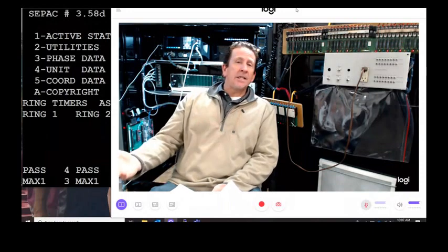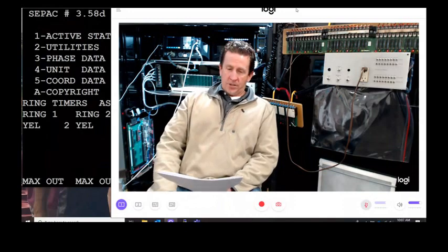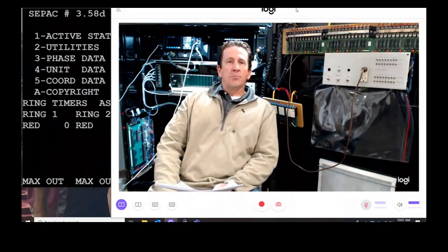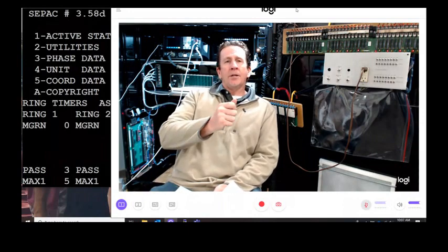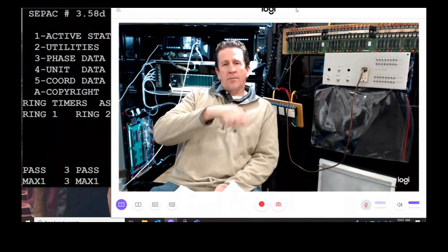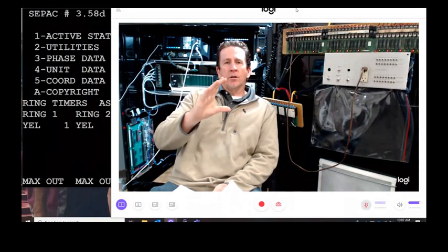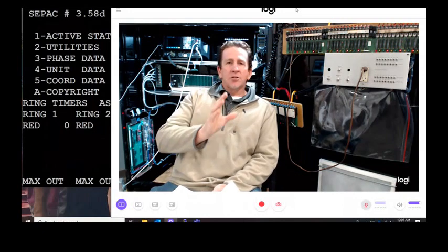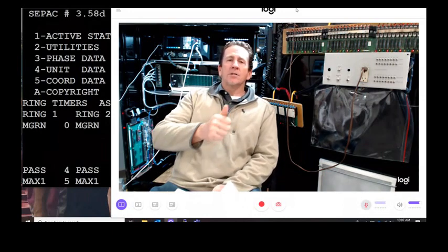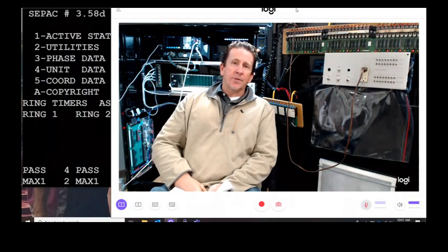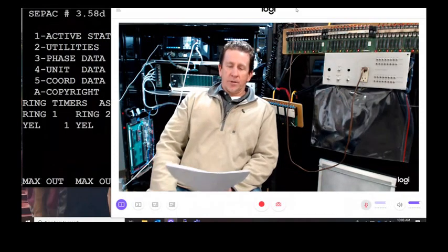We take as many easy ones as we can get when we're out troubleshooting. It doesn't always have to be over the top hard for us. Same thing, BIUs plugged in properly, or you hear us use the phrase "seated properly." A BIU goes in a little aluminum chassis, and again, I'm just overviewing right now. Sometimes those chassis are a little warped, so the BIU plugs in, but it only goes in halfway. So sometimes you gotta have them pop in. It could be something as simple as, it's not just the harness, it's the BIU isn't seated in properly.